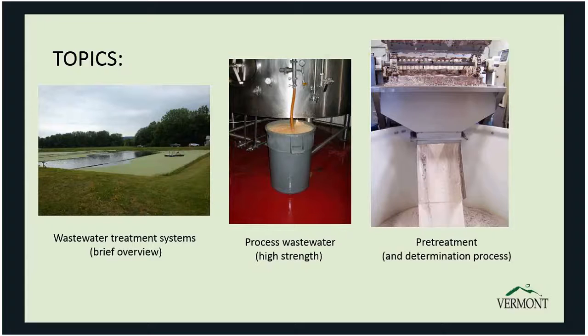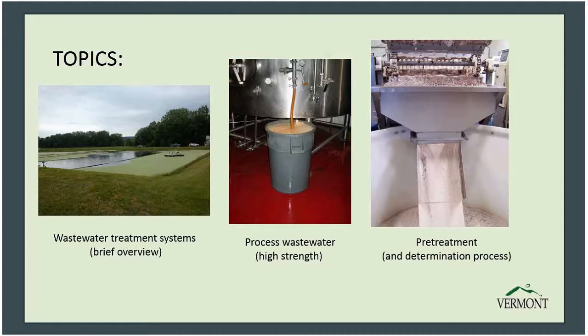And you can see in these pictures left to right, the left picture being what you might find at the beginning of a wastewater treatment plant, which would be some screens and mechanical ways to remove solids. Center picture is where you might do some biological removal. Now, these wastewater treatment plants are using natural bacteria that are occurring in the wastewater to break down other contaminants. And the picture on the right is of effluent from a wastewater plant, looking very clear as it should, going back to the river or lake or receiving water.